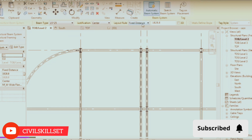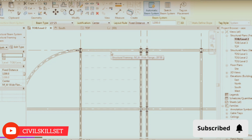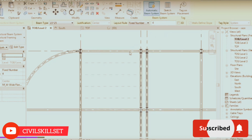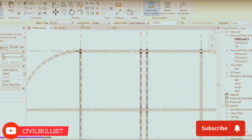Then it says, what's the layout rule? There are two common options, fixed distance, we know it. For example, fixed distance 1.20, right? Or I want it to be fixed number, for example, 4. In each of these spaces, I want 4 to be placed, right? We know that if it's fixed distance, there might be an extra part, right? So if this extra part is created, we will go for justification.